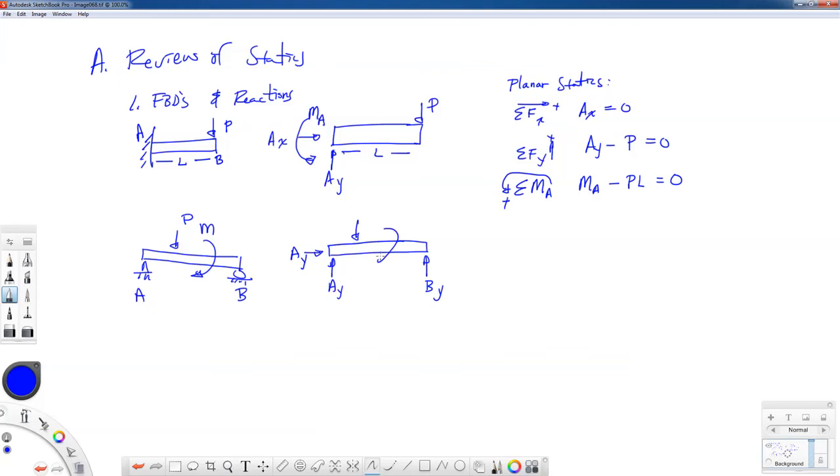Now there's one thing I want to point out about these roller connections in particular. Schematically, they're represented like a ball or a marble that's just sitting on a table. We have maybe a ruler that sits on top of that. While that is a fine representation of a roller type connection, the idea is that it allows for translation in the horizontal direction while restricting any translation in the vertical direction. So in real beams that could support loads that go both down and up on a beam, the roller is really a captured roller type configuration.